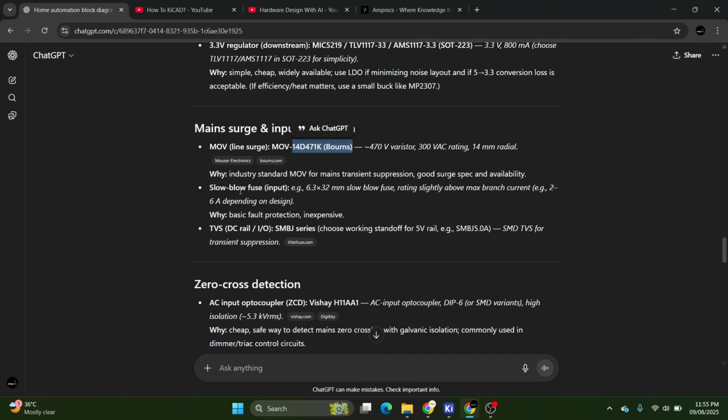And apart from this, we have to use a fuse also, and the fuse is one of the most important devices in such an application. If there is high current consumption, or something unexpected happens, this fuse is going to always save your device. So it is a good approach to use a fuse in your project, and GPT-5 is exactly suggesting us to use it. It is really good. And again, it is suggesting us to use a TVS diode on the output side.